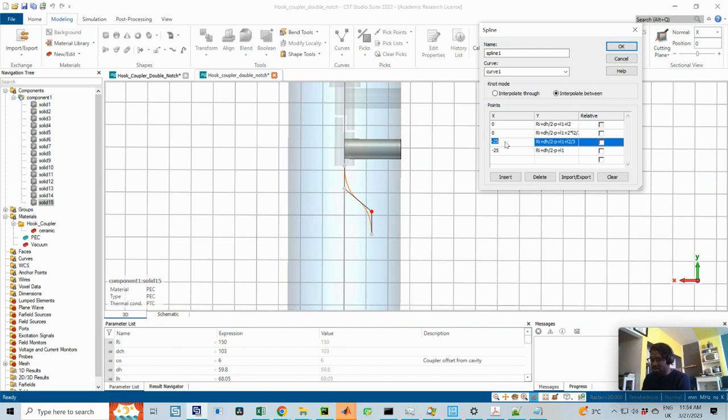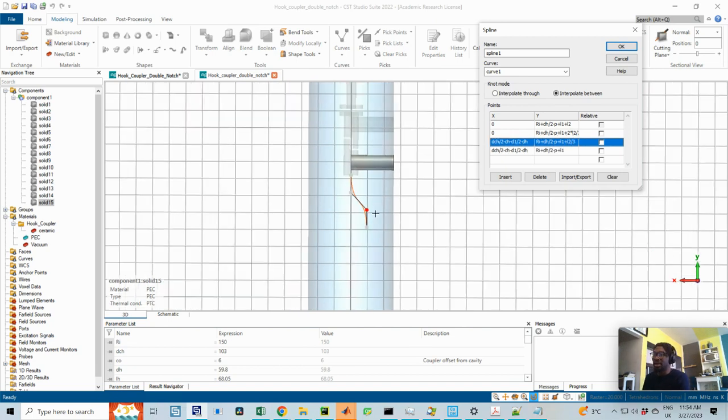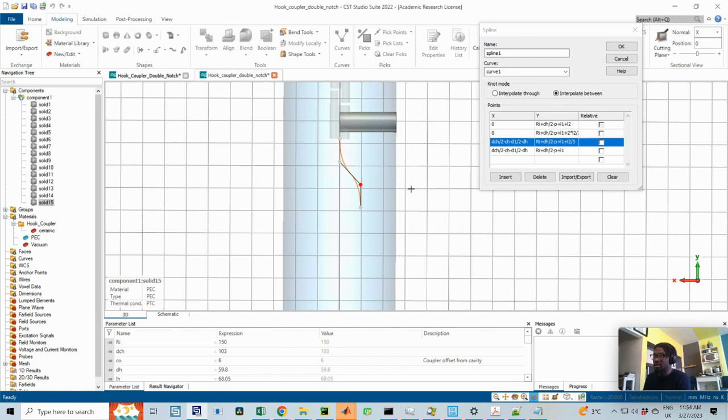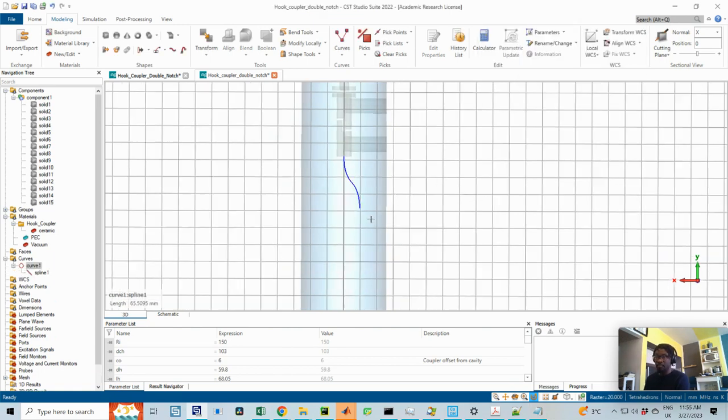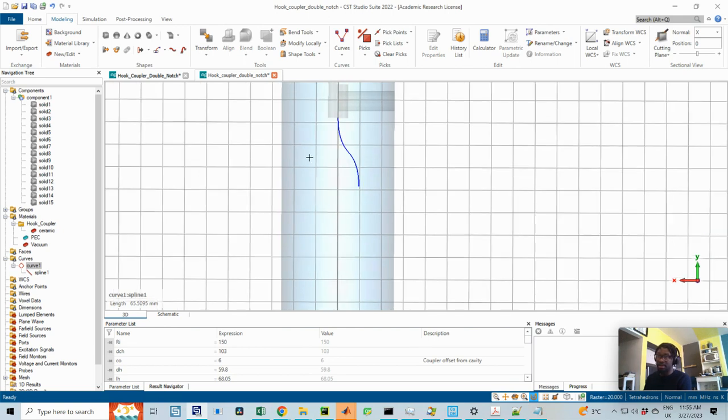So I have what I just said: dch divided by 2 minus ch minus d1 divided by 2, then minus dh. I think that should be correct. Yes. So exactly the same thing, dch divided by 2 minus ch minus d1 divided by 2 minus dh. Yes, so there we have it. If there was any mistake, we would always be able to come back to it. So then you click on OK. Now that gives you the first part. Now this is just a curve.